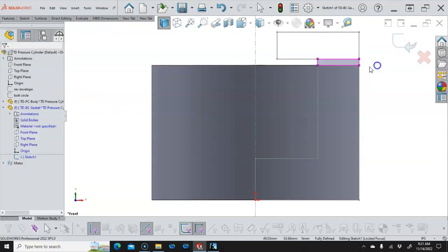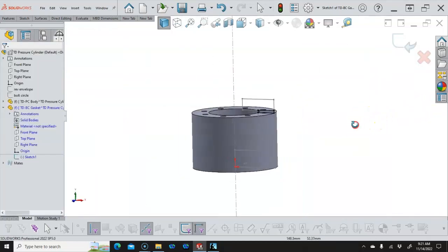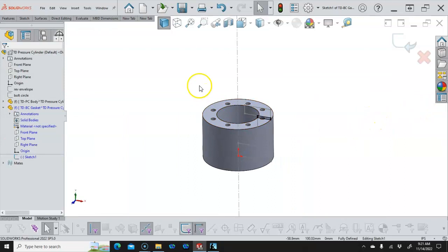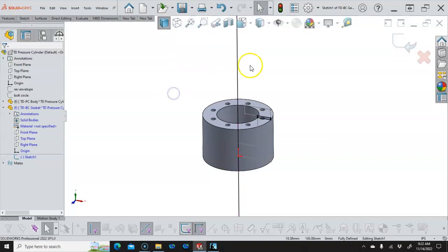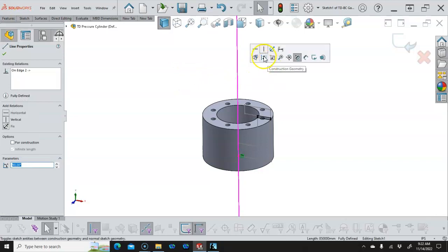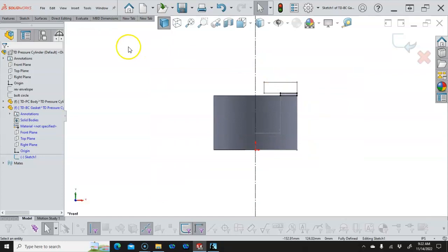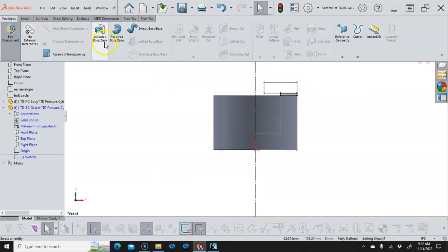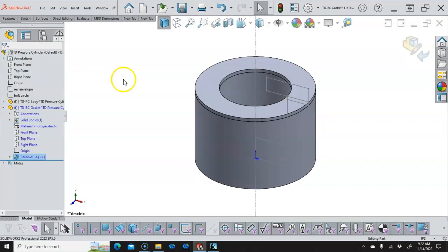and I saw that grab the midpoint. At least I want to double check. Yeah, it went coincident. It doesn't look like it grabbed the midpoint. So again, we will convert. Let's stay with the sketch convert, because I don't remember if that's on the S key sketch. And then we can revolve features, revolve boss base, and OK.